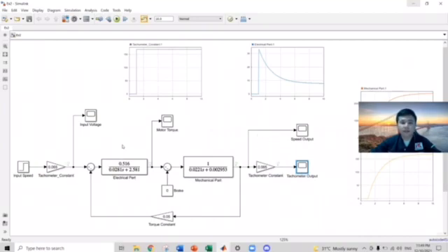This is because there is some copper loss or magnetic loss inside this DC motor. After we run the simulation for motor speeds from 400 to 2600, we observe that the motor speed is directly proportional to the input voltage and also the tachometer voltage.